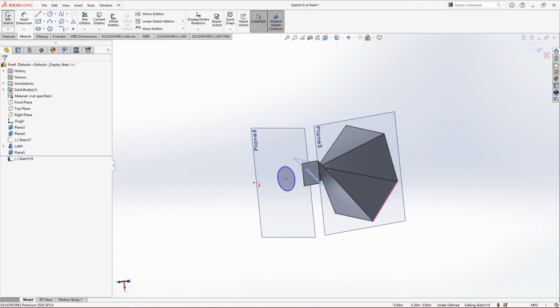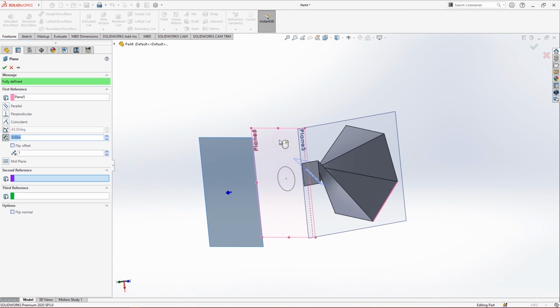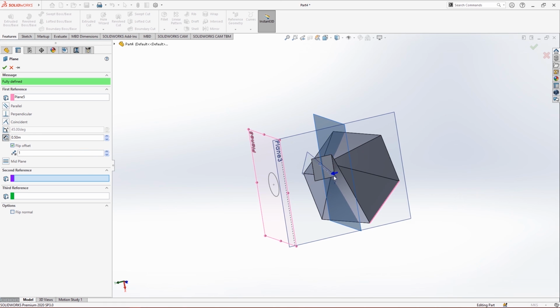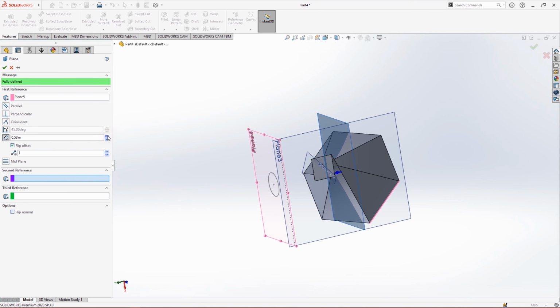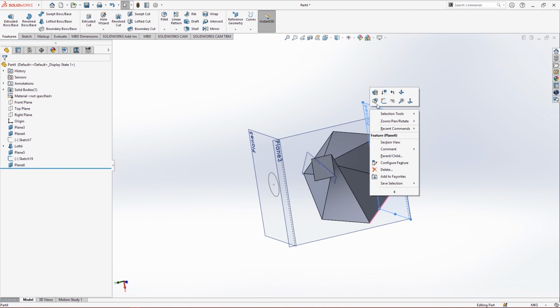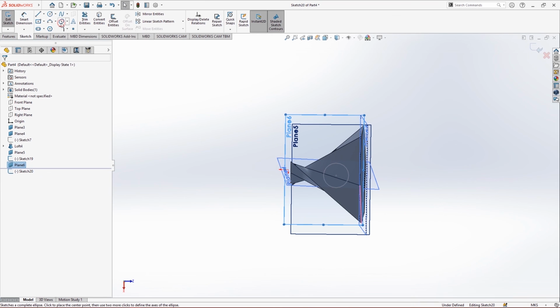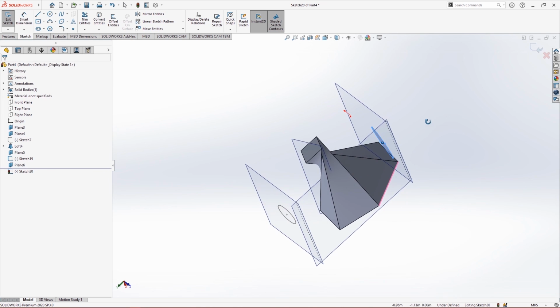And we make another surface. So we make another plane with the help of it. Flip offset means you change the direction, and yes, increase the distance. So I'm choosing sketch also on it because I need two sketches. So I will choose a small sketch here, like, okay, let's make an ellipse. Okay, we have two shapes, and we will make a lofted cut.